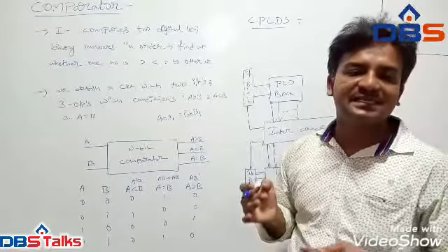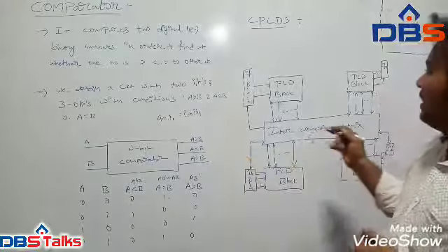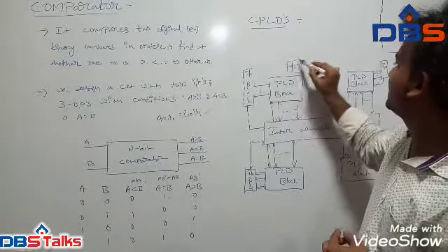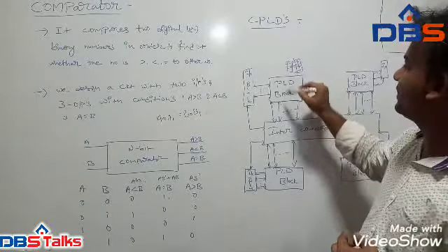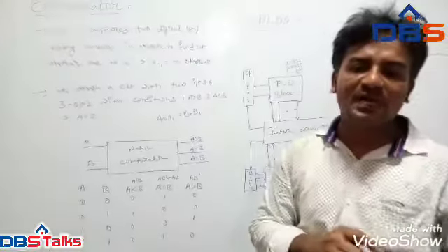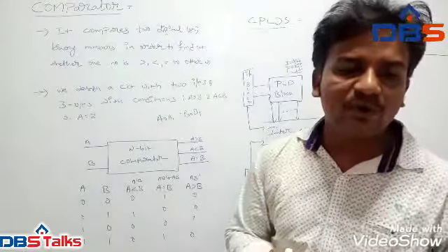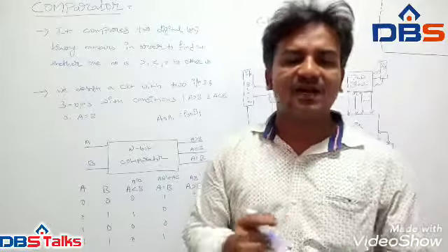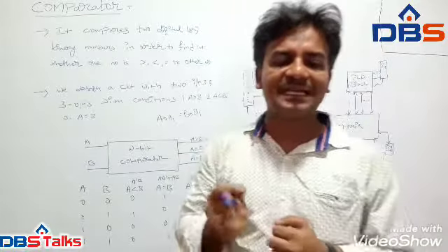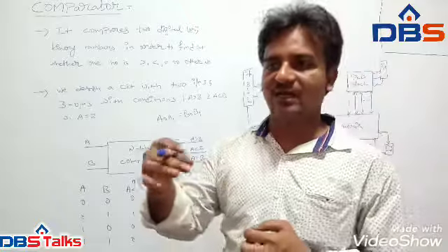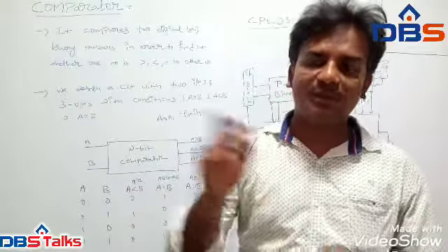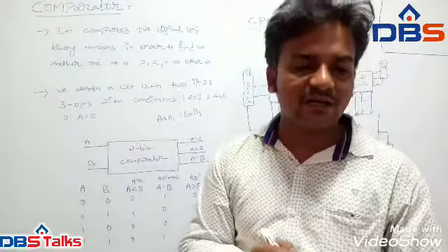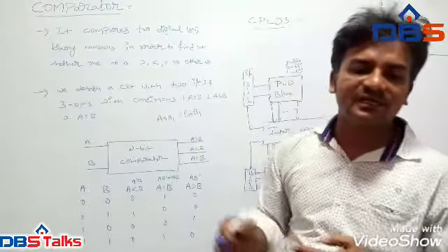In this, the basic CPLD cell is also called a macro cell. The individual cells present within the PLD blocks are also known as macro cells. It is composed of AND gate arrays and surrounded by the interconnecting area. So this CPLD offers high speed. Each circuit block is similar to either a programmable AND plane or a programmable logic plane, whether it may be a PAL or PLA, connected to a set of interconnection wires.